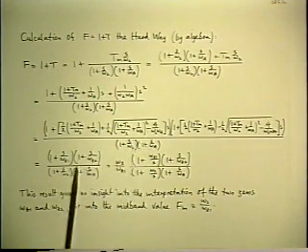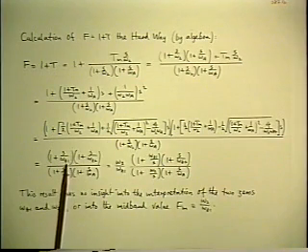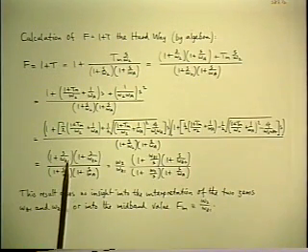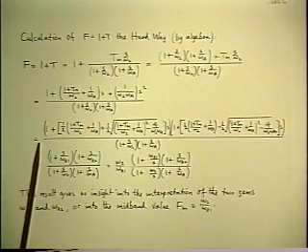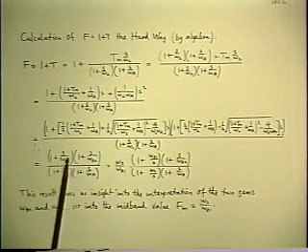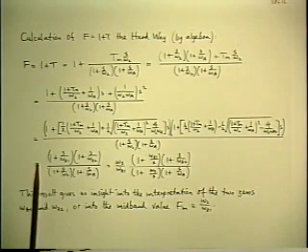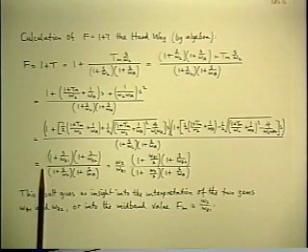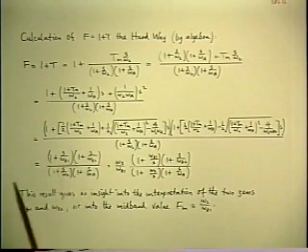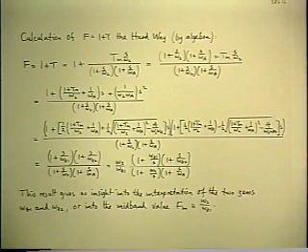And even if you just define it and say as an omega z1, as I've done here, notice that what comes out of the algebra has unity coefficient in front with normal zeros and normal poles, so you've effectively chosen the zero frequency asymptote as reference, which is 0 dB. And who cares about that one? The Tm has vanished. The Fm has vanished.